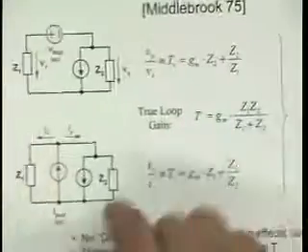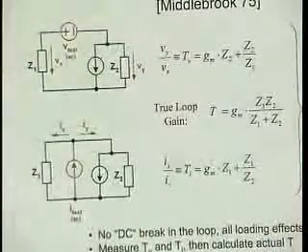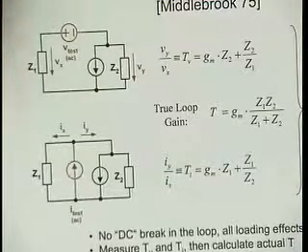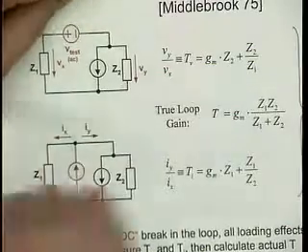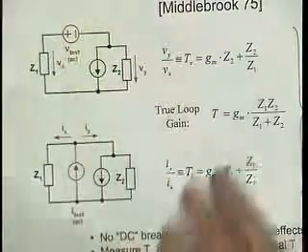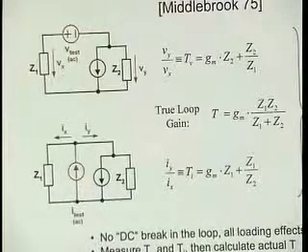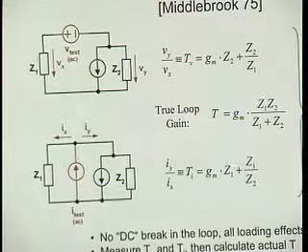In practice, doing that is quite a bit of work with SPICE. One thing that I found to be quite convenient is I put my entire circuit, my entire amplifier with feedback and everything, don't open anything into a subcircuit, and I find a point somewhere where I can break all feedback loops.